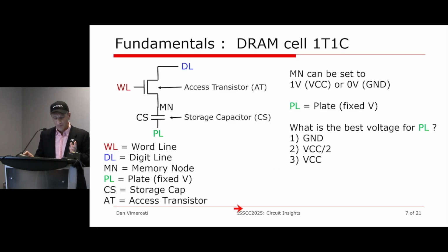And I have to say this. This is better for some reasons and maybe not perfect for other reasons. There is no correct answer. Always there are only pros and cons for each possible solution. And you will see it also later. There is one major problem, though, in DRAM, which is the oxide thickness for the storage capacitor, and that overwhelms everything else.